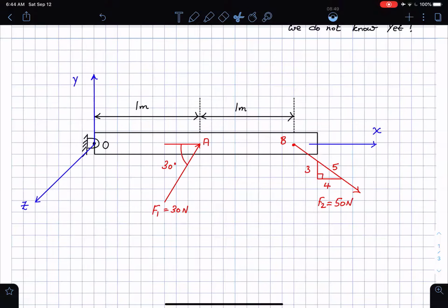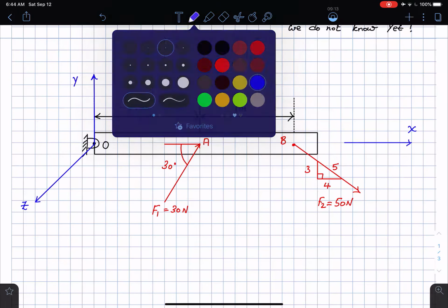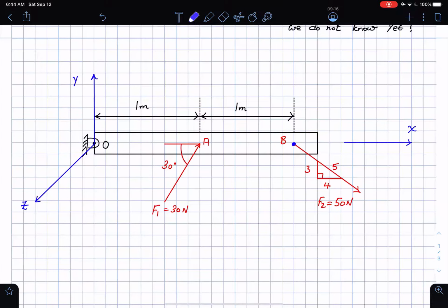So what am I going to do? The first step I will do in any problem I see is, okay, hey, I want to take these forces and break them into their components, because they are at an angle. So let me do that. Okay, so let me take this guy and bring it on here. This is the point of interest, which is the point B. I guess that doesn't let me select it. That's okay. So I'm going to take this force and break it up into its components, starting from the point of application. Please always notice my components always start from the point of application. The point of application of this force is the point B, which means that my components are going to be starting from there, in the horizontal and the vertical directions.